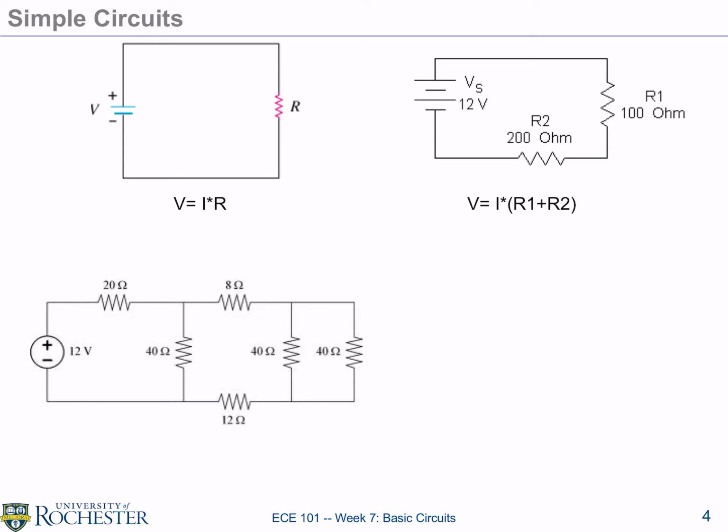And you've probably dealt with parallel equivalence. What about two resistors having the same resistance? You can convert that into a single resistor of a certain value, in this case 20 ohms, and then you can subsequently simplify this by adding the series resistors that are effectively connected to that equivalent resistor, and then you find out that you have another 40 ohm resistor, and so on and so forth, and you can see through this circuit.